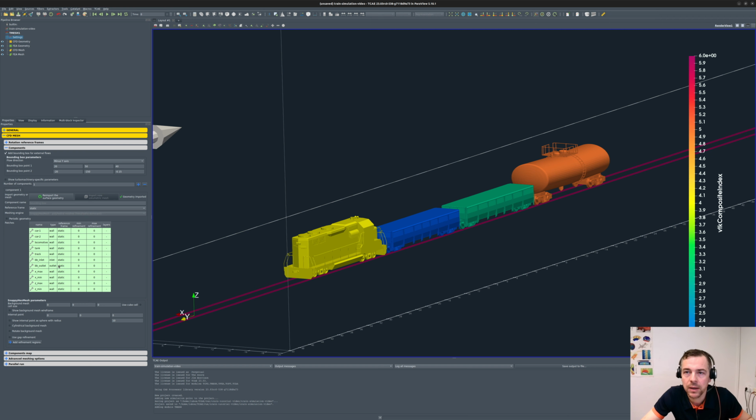I need to say a couple of things. So for example, the walls of the virtual tunnel are virtual. So I will say I need to go with symmetry wall type. It's a kind of boundary condition which says there's no friction at the wall, but the bottom is the standard wall.